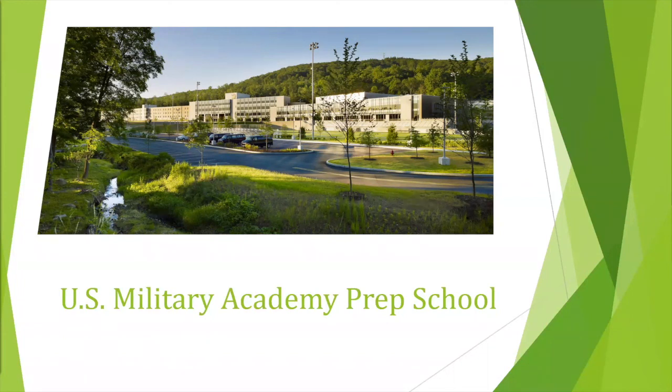So what we did for that was all open swales on the exterior roadways that discharged into the stream. And then we had a small amphitheater that had filter strips in between it and the back to catch the runoff. So everything kind of formed around the building. And again, completely sustainable. There's no connection to a closed system, which is always, I think, a key element to having successful stormwater management with green infrastructure practices.